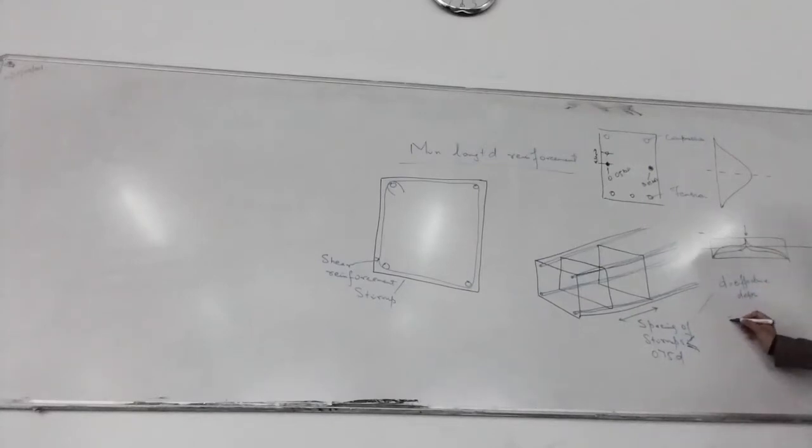And what was effective depth equal to? Overall depth minus the cover, minus phi of the stirrup, minus half times phi of the longitudinal bar. Or you can say D, capital D, which we designated last time: D minus phi of S minus half times phi of L. Phi is the diameter of the bar, measured from the outside.